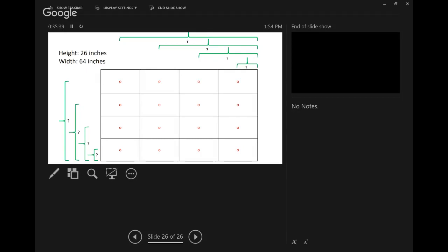One group is going to measure all 16 rectangles with the sash. Imagine this is the face. You're going to open the sash all the way, basically as high as it'll go. It might alarm, and we'll silence the alarm, which we normally shouldn't do, because the face velocity is going to drop below what it's supposed to. That's why it's going to alarm. But we're doing a test, so we're not actually using any hazardous chemicals.